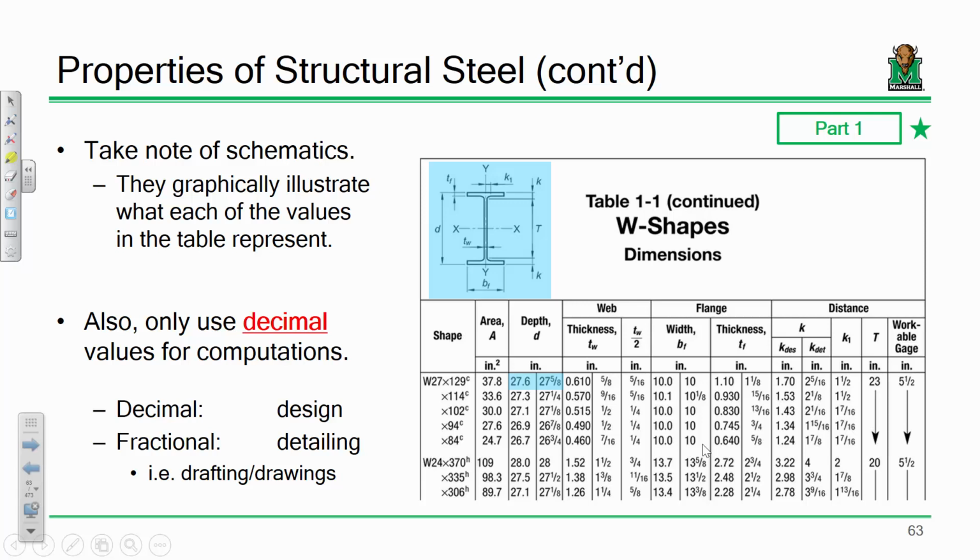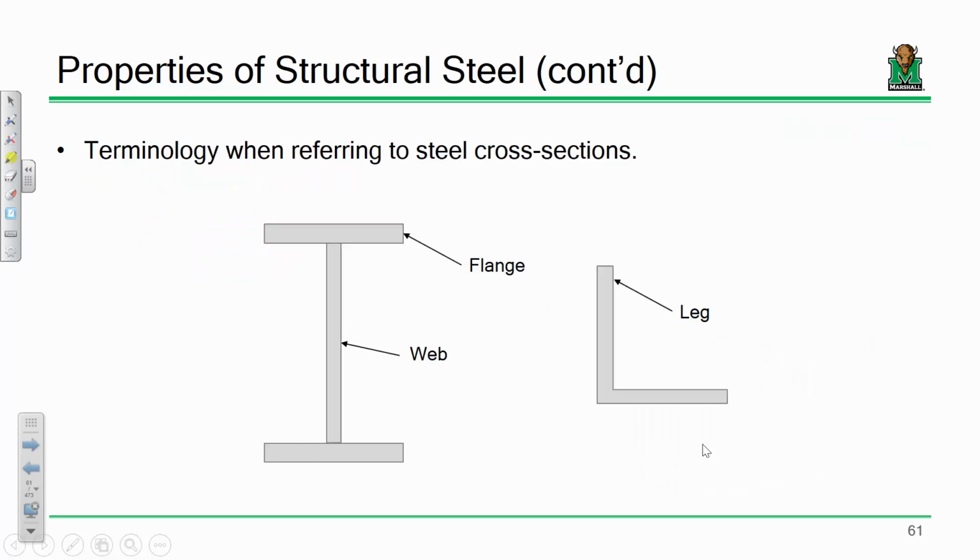Yes? What are the C's and H's and V's? That is a great question. The question was what's going on with the little C's and H's and V's. That will become clearer when we talk about columns and beams, but the short, quick, and dirty answer is this: when you have things in compression, like things being pushed on, they can buckle. In structural engineering and steel design, we really are focused on two modes of buckling, either global buckling or local buckling.